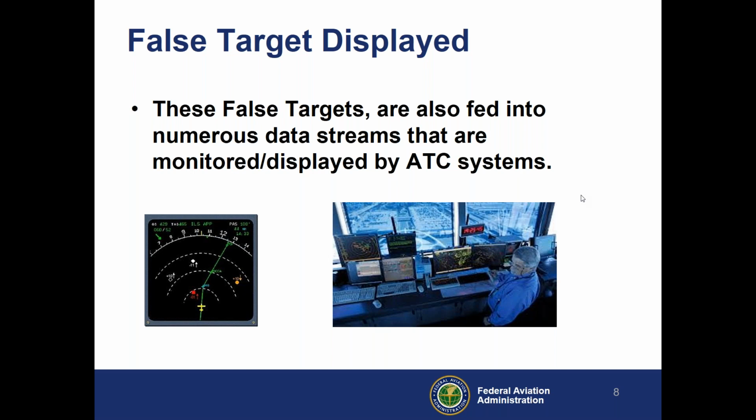But nowadays, if you're being picked up by the ADSB receiver site, you're in the national composite traffic picture. And so anybody looking at that will see that target. And also, it's a very good indication if you're being picked up by the ADSB site, you probably have enough leakage and such that you're going to pick up an airplane flying over you with a TCAS doing their inquiry and respond to that. So it's a much bigger problem,